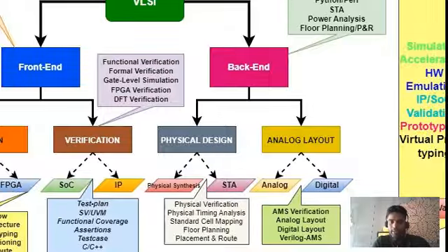hardware. That's what the actual pre-silicon validation does, for the bigger designs, for the SoCs and all. For SoCs, there will be billions of logic gates. We cannot fit that into one or two FPGAs. That's where the emulation platform comes in, which will have multiple FPGAs interconnected together. You can place your design over there and do the hardware verification. It will be done in hours, whereas in simulation it would run for days and days. It saves a lot of time.